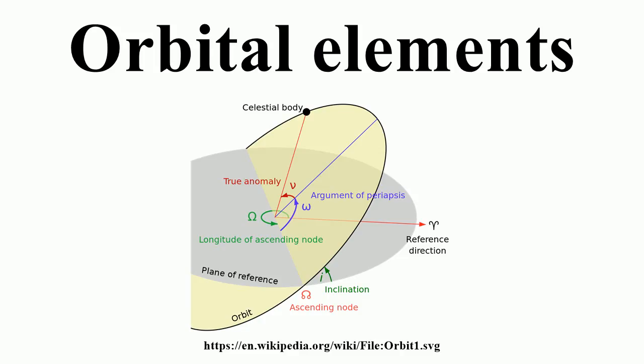Required parameters given an inertial frame of reference on an arbitrary epoch. Exactly 6 parameters are necessary to unambiguously define an arbitrary and unperturbed orbit. This is because the problem contains 6 degrees of freedom. These correspond to the 3 spatial dimensions which define position, plus the velocity in each of these dimensions. These can be described as orbital state vectors, but this is often an inconvenient way to represent an orbit, which is why Keplerian elements are commonly used instead.